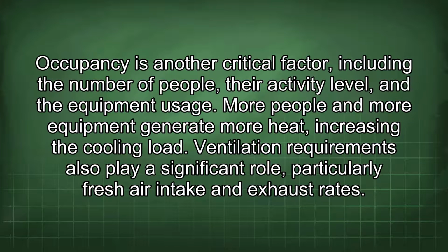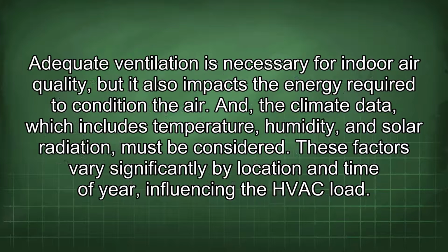Occupancy is another critical factor, including the number of people, their activity level, and the equipment usage. More people and more equipment generate more heat, increasing the cooling load. Ventilation requirements also play a significant role, particularly fresh air intake and exhaust rates. Adequate ventilation is necessary for indoor air quality, but it also impacts the energy required to condition the air.